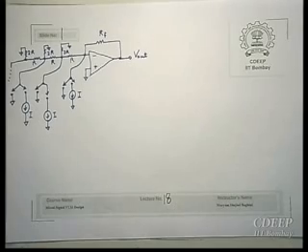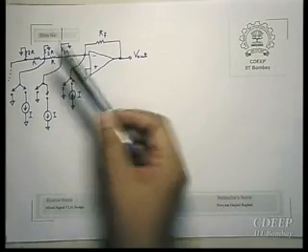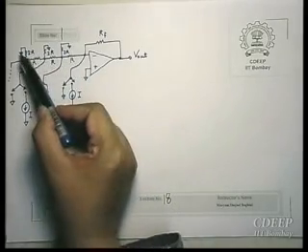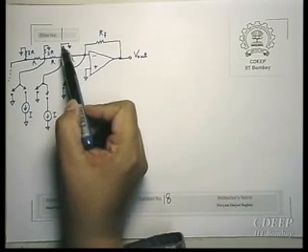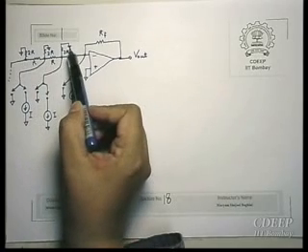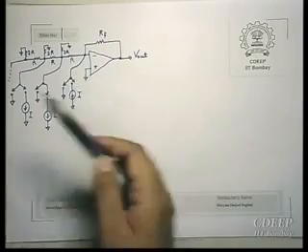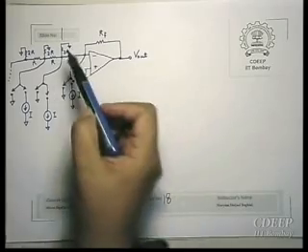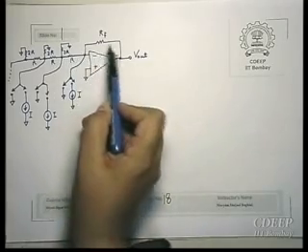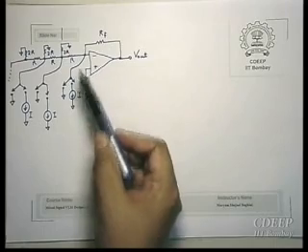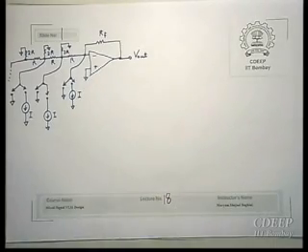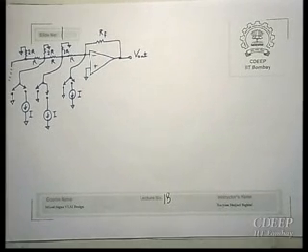Instead of controlling these points, which are connected right now to ground, the bottom terminals of the 2R resistors to V full scale or ground, because what it was doing was actually injecting current to this node and then to RF, now we are injecting current directly by using a current source, and that current source is constant. The values of resistors again are not binary scaled, it is an R2R ladder.